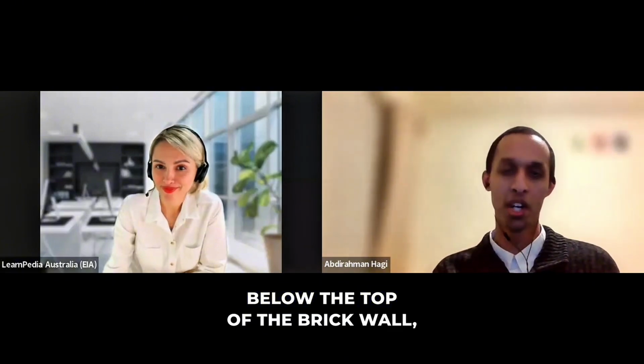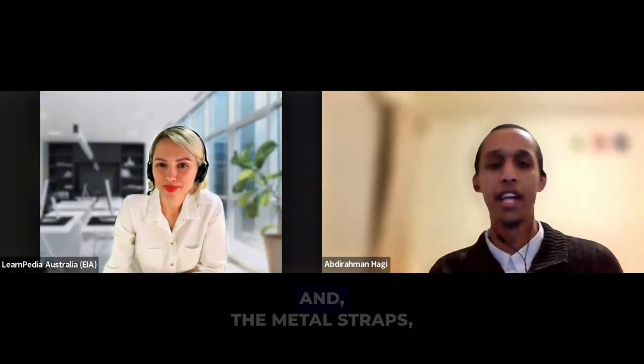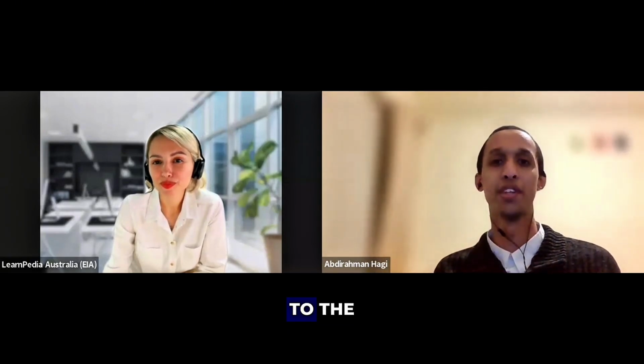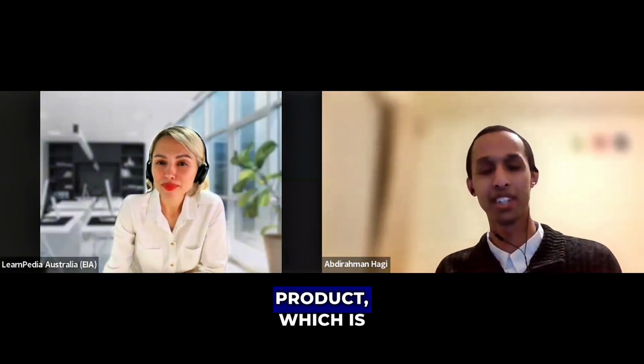To achieve this, metal straps can be embedded 12 courses below the top of the brick wall. The metal strap is bent upwards, passed over the top of the top plate and secured using nails. Once it's fixed, you can use Pryda triple grips to connect the timber trusses to the top plate. Alternatively, for a faster installation, you can use another Pryda product, which is Pryda Speed Truss connectors.